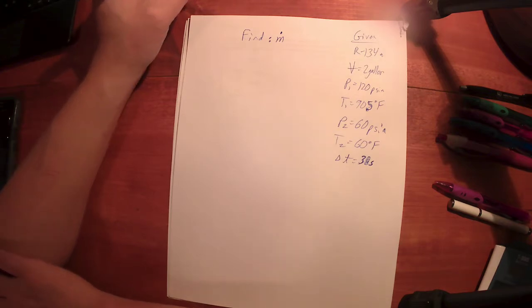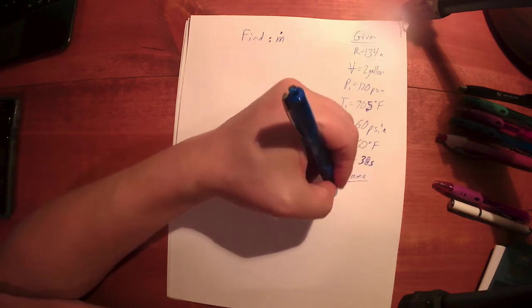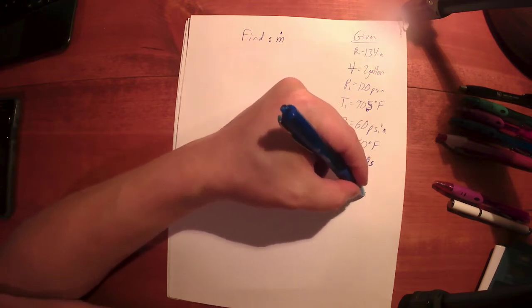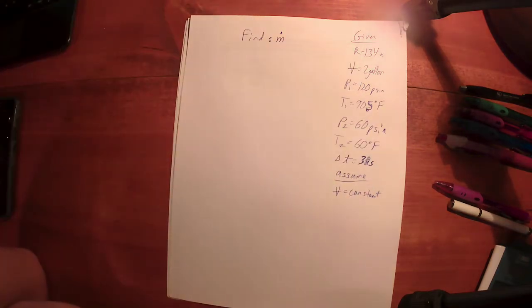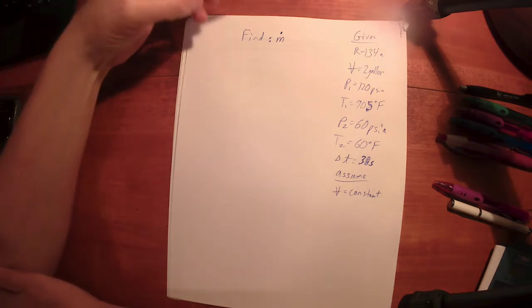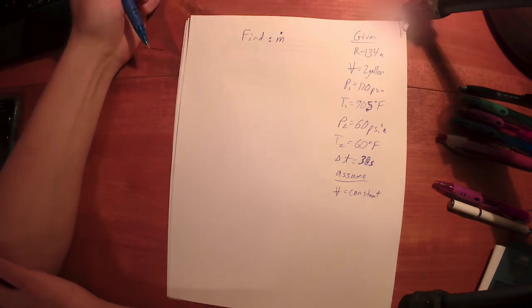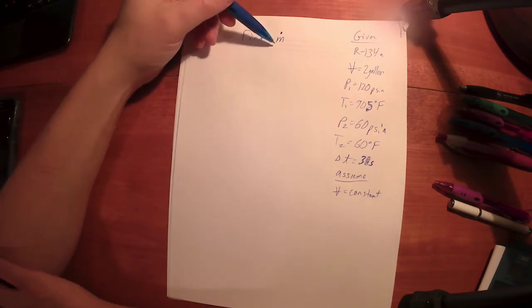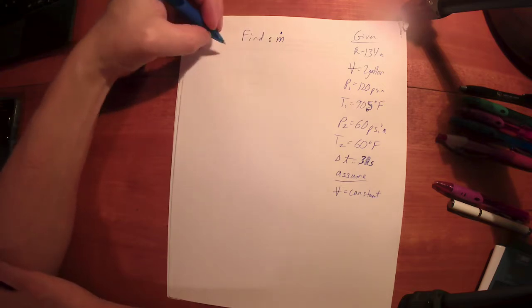So we're going to make some assumptions here. They didn't tell us that it's a rigid tank. That would have been helpful, but they didn't tell us that, so I'm just going to assume that it's constant volume. That's a pretty safe assumption, unless the tank got dented. They didn't tell us anything about a dented tank, so let's assume the constant volume. Okay. What else are we going to do? Well, let's talk about what tools we might use to try to figure this out. We could maybe use conservation of mass to figure out a mass flow rate. That might be helpful, but I don't know that we would have enough information to pull that off.